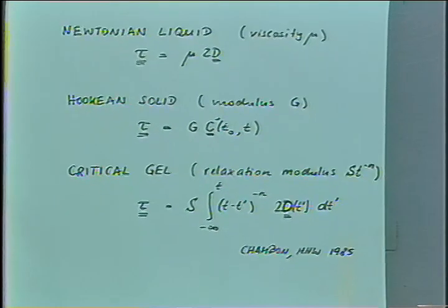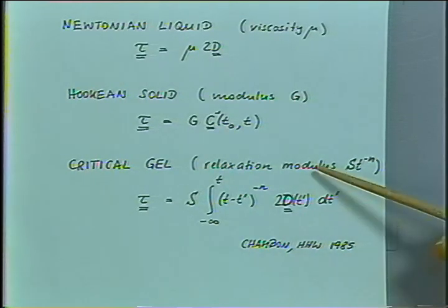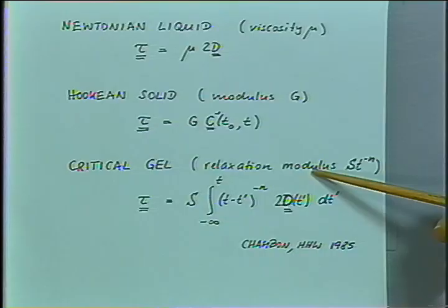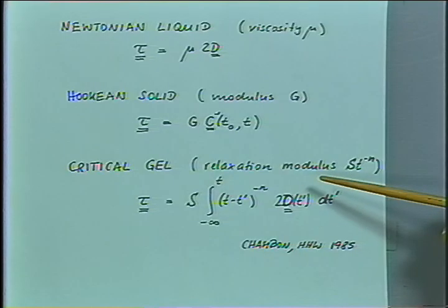It turns out that for viscoelastic materials, there is a very simple equation for the behavior at the transition from liquid to solid. You could, for instance, look at a cross-linking polymer, maybe an epoxy, which in the beginning, when the reaction has not even started, is low molecular weight, which tells you it's a Newtonian liquid in the beginning. And then you react this material to completion.